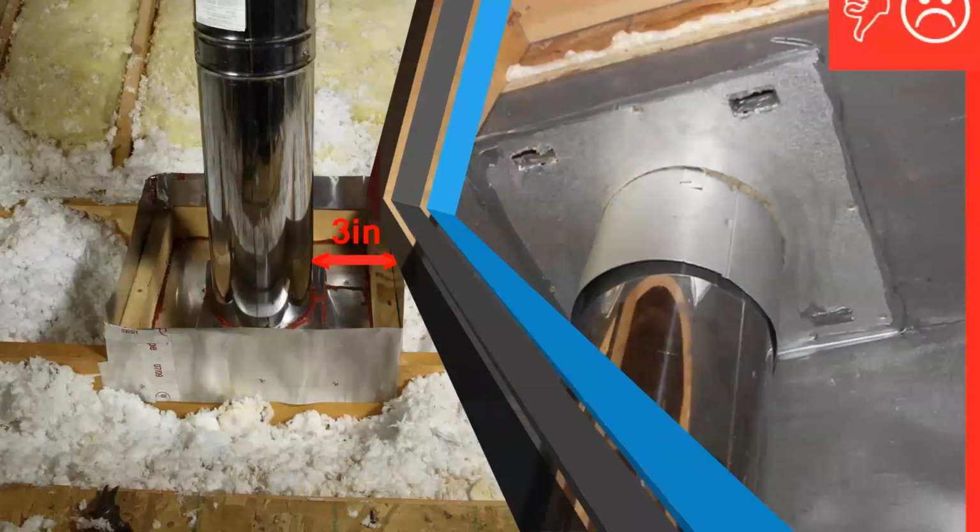And then we talked about it a minute ago, and this is the photos for that. Not as easy as filling the gaps between the flue pipes. Most of the time, contractors will use the excuse of, I can't seal the gap between the pipe and the flange. As you see on the left-hand side, the photo shows it's being done correctly with fire caulk. It's a specific color so that the fire marshal or building official can assure that that's a fire barrier or a draft stop for fire. It's always an acceptable means to have it done this way.